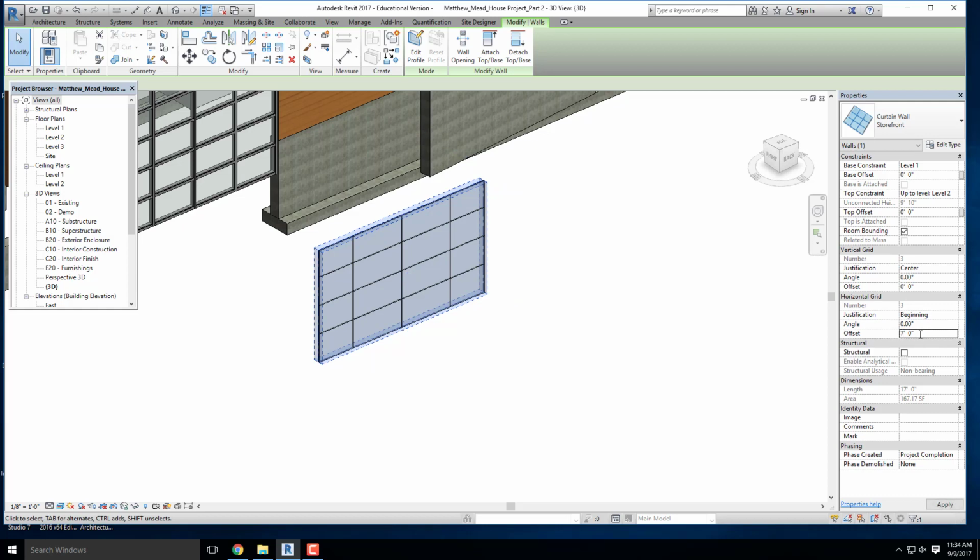Okay? What that does is it's saying, I have a group of parameters. I want that spacing to be 2.5 feet, but I want that to start at 7 feet. So you're basically creating a starting point for where those type properties will begin. Okay, so that's what the offset will allow you to do. So if you don't want that rule that you created to start at a particular point, you can add an offset and actually adjust that starting point of where that spacing might begin. Okay, any questions about any of that?